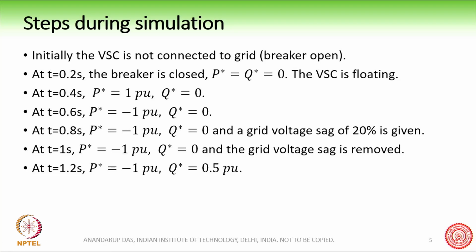Otherwise, if you turn on the breaker while the capacitor is fully de-energized, a huge inrush current will happen and the breaker will open. Then you cannot actually run the system.